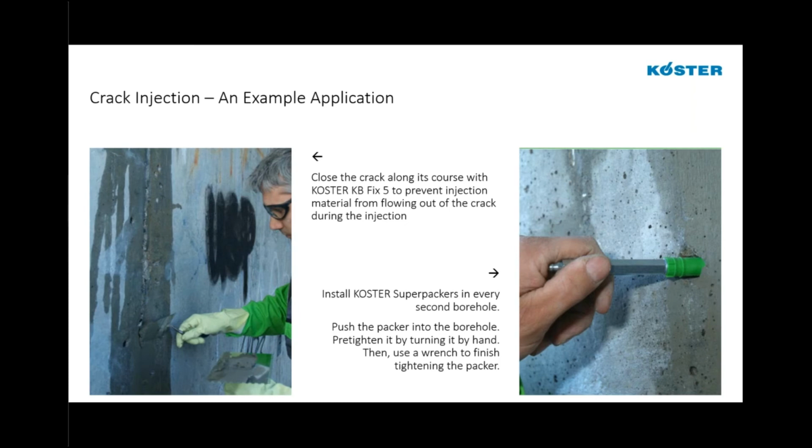The other side of that coin is how do we monitor the travel of material up the wall. Most times when you inject, obviously from top to bottom, you can monitor the material and the foam by looking at the crack up the surface. If we surface seal, we're very unlikely to see material moving up the crack.